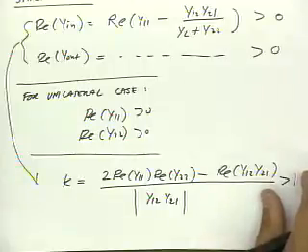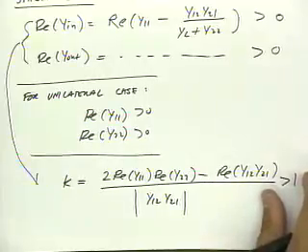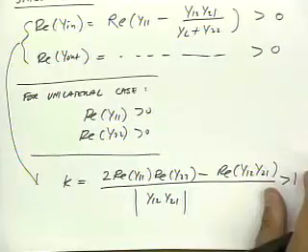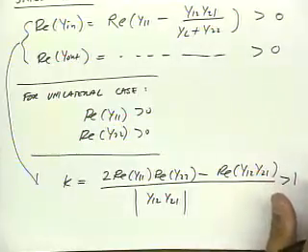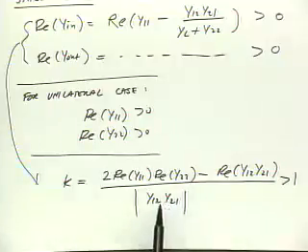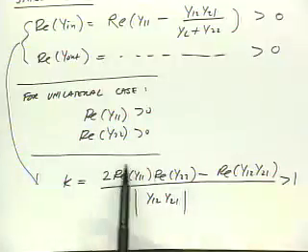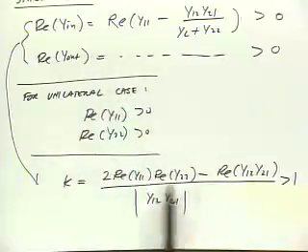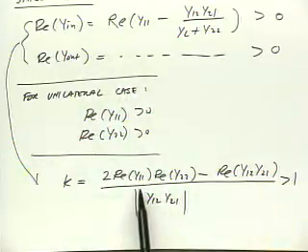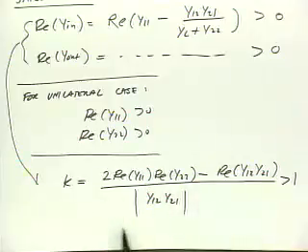All right. So a couple of things to notice. This expression here applies for a two-port. It has nothing to do with the input port or the output port. This expression is invariant if I change ports 1 and 2, right? So it's a condition for the entire two-port. That means that if port 1 becomes unstable, by definition, port 2 can also be unstable, and vice versa. So stability is a property of the entire two-port, not just a property of one of the ports.